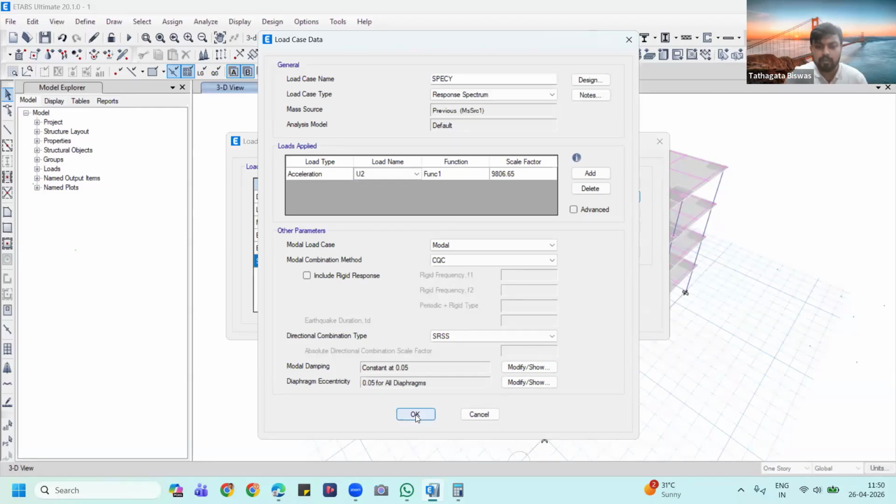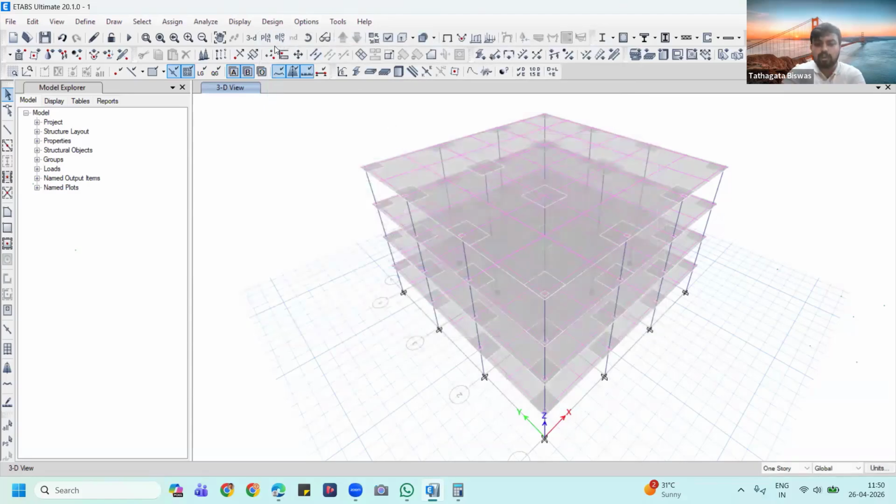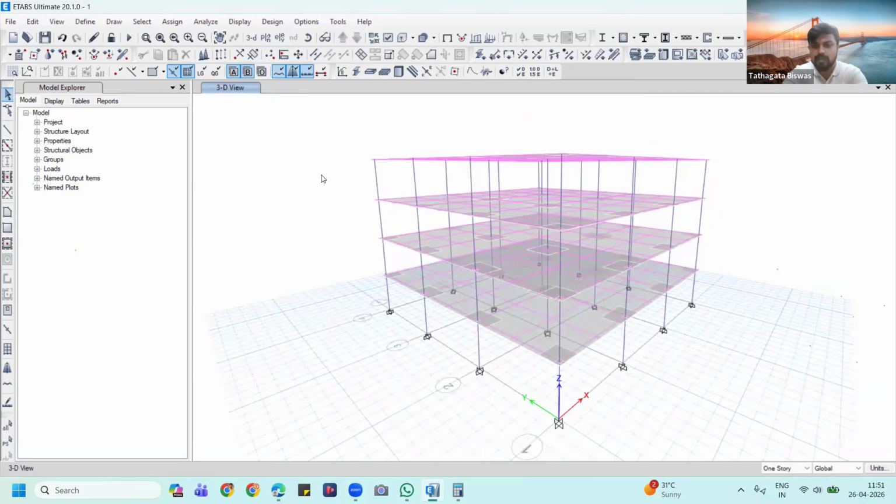Now we need to make it okay. Another very important thing. Since I have taken this model, which is a prototype, called a flat slab model, for flat slab the R value should always be 3. It should not be 5 as per the code. So do not consider the systems which I have taken. This is just for showing you guys. This is not the actual project that I am doing. How the methods should be done, how the steps should be followed, that I am basically trying to guide you on. You need to take the proper methods or proper values from the code as it is.